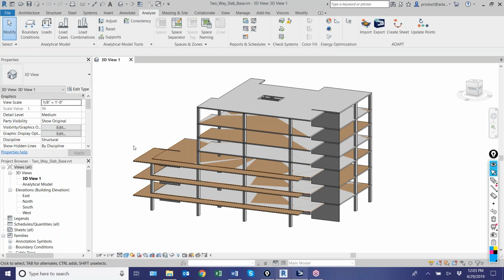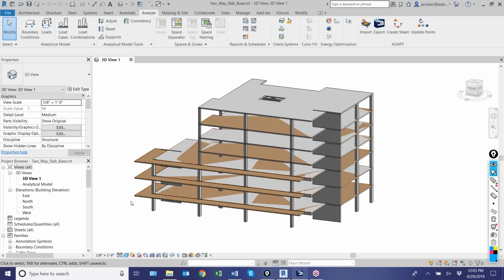We access the Revit API, and we're looking for certain things when we extract and write the data. This file gets written to an IMP format, which is what ADAPT uses for integrating with Revit, eTabs, Tekla Structural Designer, any builder-to-builder models that you want to interchange within the Builder platform, ADAPT's own platform, you would use IMP also. So this is a pretty standardized format that we use for extraction and then importing into Builder.